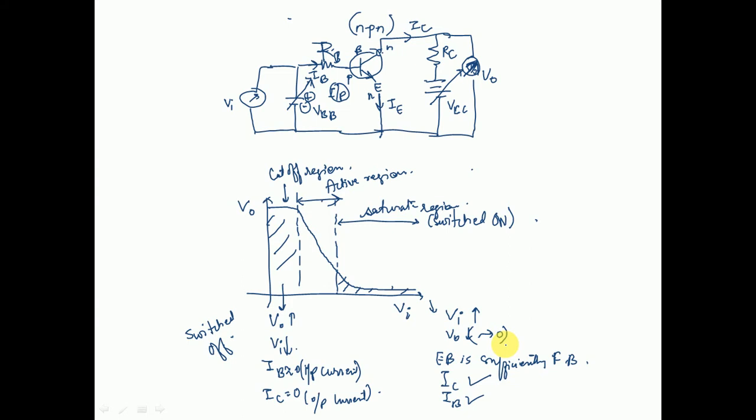The input voltage is becoming very, very high, and the output voltage is becoming very, very low. So from greater potential to lower potential, the current will start to flow. That is the rule. Please try to understand what I am saying carefully. If not, then please replay it. When the transistor is in the saturation state, maximum IC is flowing. Not even 1 milliampere of extra IC can flow now. So this is the maximum IC flowing through the transistor, which is obviously your switched on state.